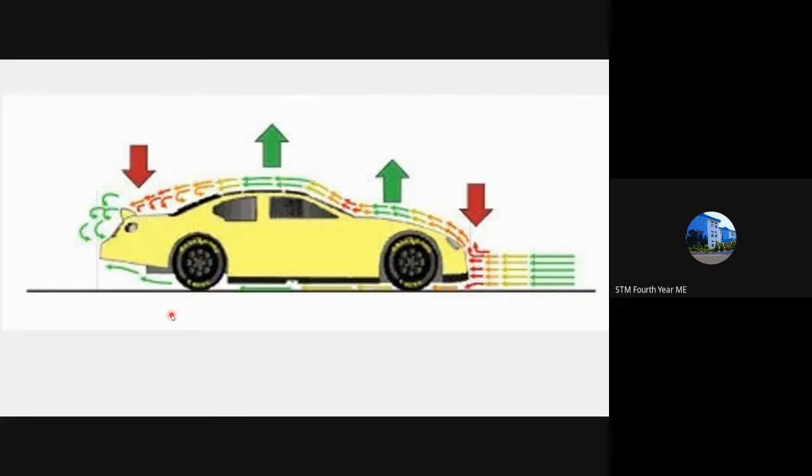In some designs, at this point also we will obtain positive lift, and even if you obtain positive lift here, it does not matter, because due to this upward motion, this portion of the vehicle still tends to move downwards. Only if this becomes positive lift, the vehicle overturns.